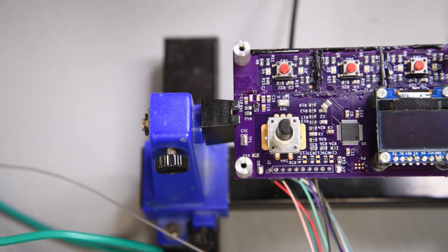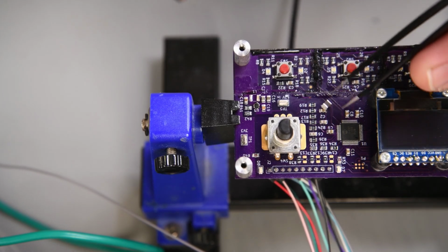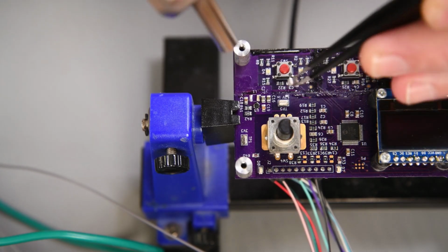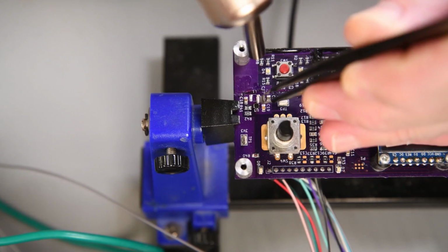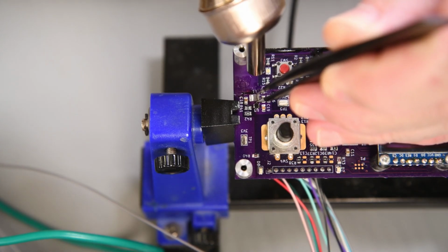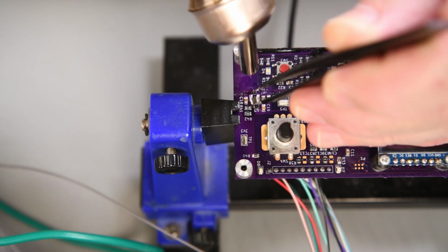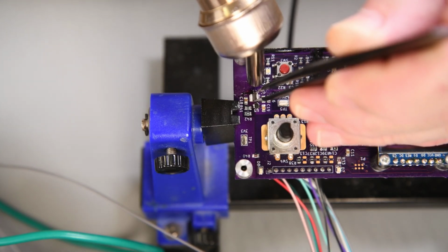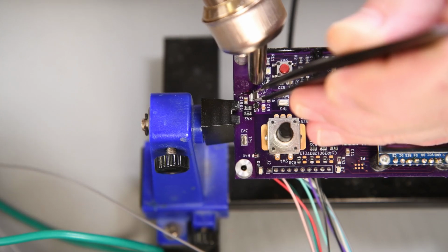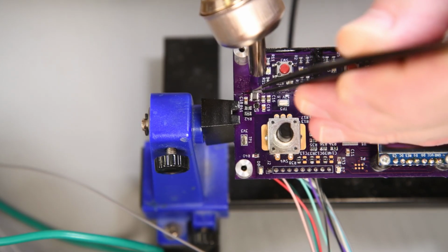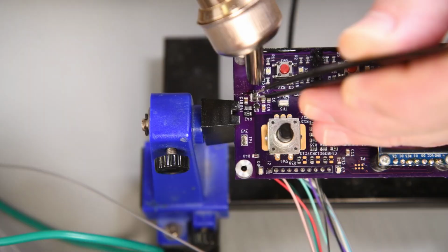It's working. Output is 3.3 volts. I didn't even check at the time to see what the consequences of using a smaller inductor were. I just put on my to-order list the 47 microhenry 1210 case inductor and a 10 microfarad 50 volt 805 case capacitor. Then weeks go by before I get back on it. It's working, so I forget where I left off, or even that the new parts had arrived.